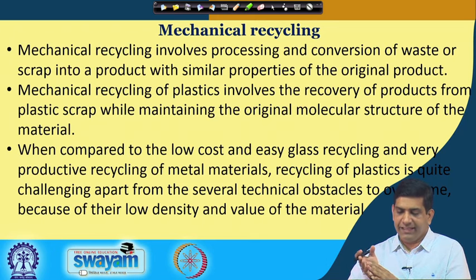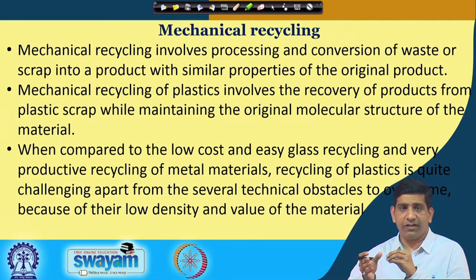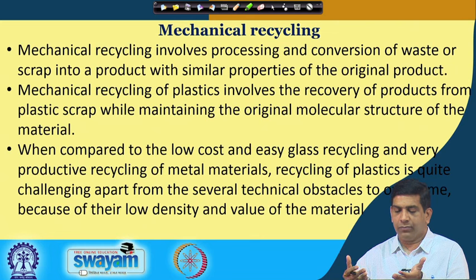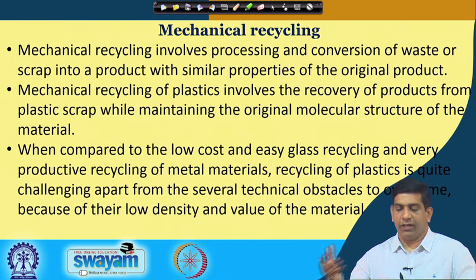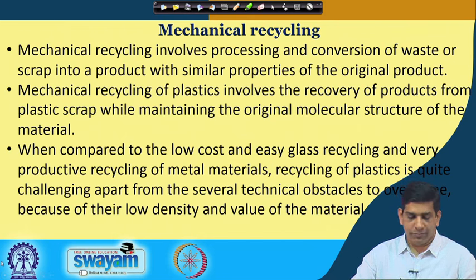Compared to low cost and easy glass recycling and very productive recycling of metal materials, recycling of plastic is quite challenging, because apart from several technical obstacles to overcome, plastics have low density and low value of the material. So, plastic recycling, other than PET and HDPE to some extent, for other types of plastic, because of the low cost, you do not get much value out of those recyclable plastics, and it becomes challenging from an economics point of view. There are also some technical obstacles which we talk about.